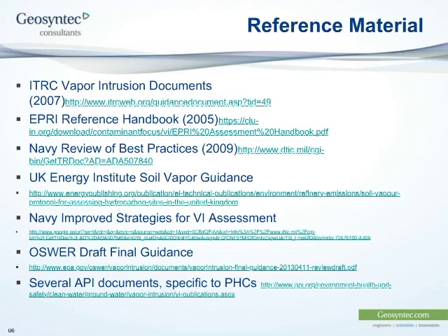The next question that I see is from Giovanni. What is your opinion on a possible starving problem the passive samplers can have? Oh, I'm glad you asked. Passive samplers are designed so that they'll take chemicals up from their environment at a certain rate. As long as the environment provides chemicals at that rate or greater, then the sampler itself is not going to cause a bias on what it's attempting to observe.